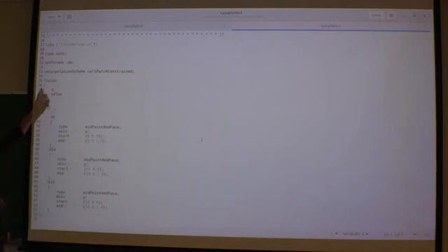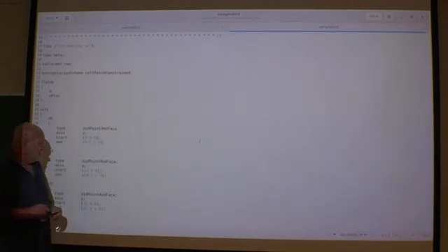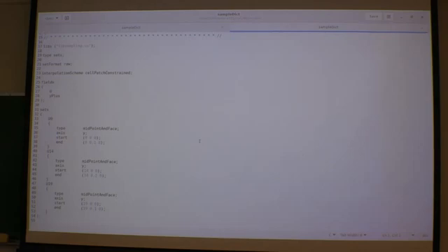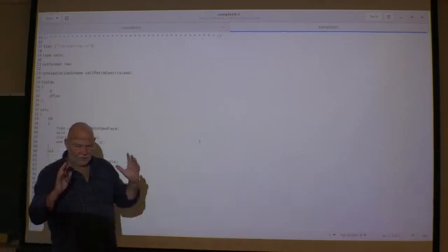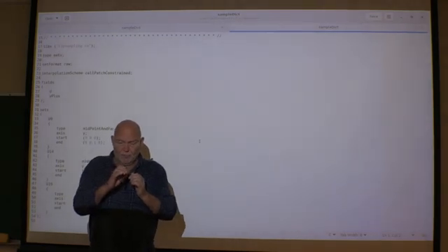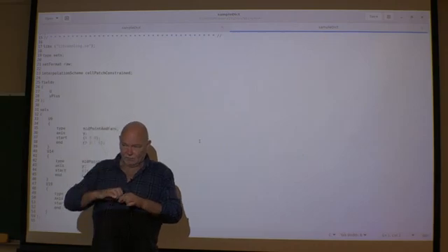And also up here, interpolation scheme, cell patch constrained. If you look at the description inside the generic sample dict, you will find an explanation of what this means. Midpoint and phase, what does he do? He takes the cell center locations, but he also takes the center for each phase along that line.